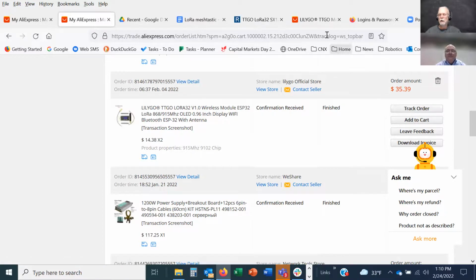One more thing, I'm not sure how LoRa works because they don't have channels, but if you go back to your code, it'll say somewhere this is either a random seed number or something. I think that's the equivalent of channels. By default, they put a 1 in there. I think you can pick a number like 1 to 33. I think that's just a seed number, as it randomly switches, because these are what they call spread spectrum, and the thing is constantly jumping through a bunch of different channels.